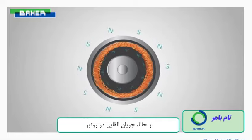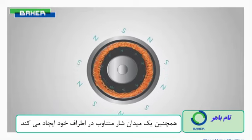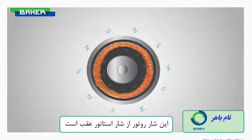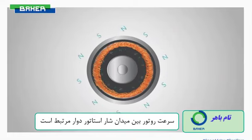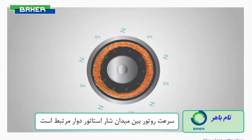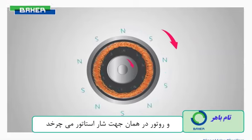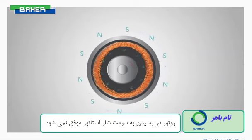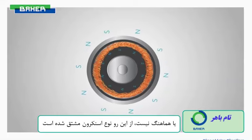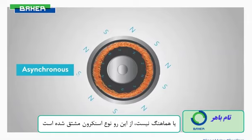Now, the induced current in rotor will also produce an alternating flux field around itself. This rotor flux lags behind the stator flux. The rotor velocity is related between the rotating stator flux field and the rotor rotates in the same direction as that of the stator flux. The rotor does not succeed in catching up to the stator flux speed, or not synchronized, hence where the type asynchronous is derived.